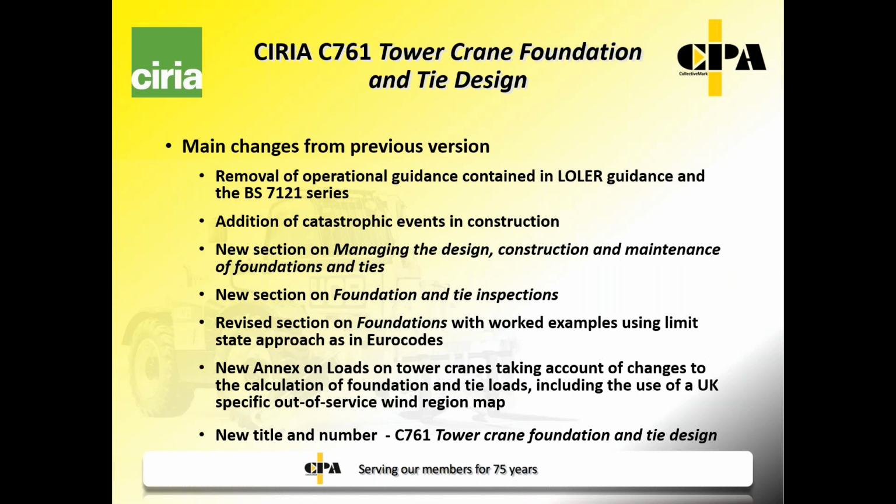We have a new annex on loads on tower cranes, taking account of the changes to the calculation of foundation and tie loads, which the manufacturers have adopted, and we include the use of a UK specific out of service wind region map. And then fairly obviously the revision has a new title and a new number.